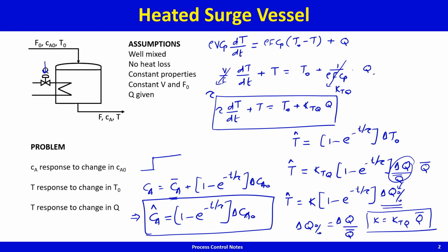Yeah, it's more convenient to work in terms of percentages, but in either case the point is: express the differential equation in terms of difference variables, and when you work in terms of difference variables or deviation variables, where the deviation is from the initial steady position, then you get very neat responses of this kind and of this kind. Yeah, so to summarize,